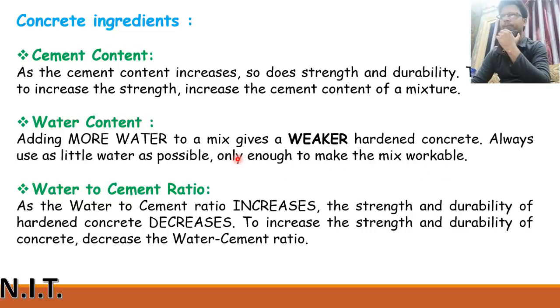Usually we use water half of the cement, but ASTM will tell you in detail. But if you don't know about ASTM standards, then you can simply use half of the cement. For example, if the cement is 1 kg, then you need to use half a liter of water, and the same mix design.